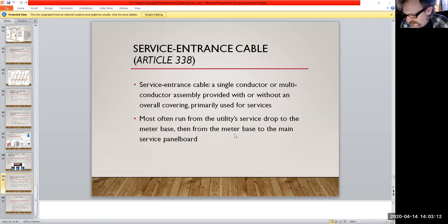But yeah, you still see some people pull a 100 amp, but if you're getting a brand new house, what would be the point? I would go with a 200 amp service. But depending on your service, that's going to dictate what your wire size is, right? Because you can always go up larger, but you have to remember, unless you're the one paying the bill, your customer generally doesn't want to pay extra for stuff if he doesn't have to, right? You want to keep your costs down.